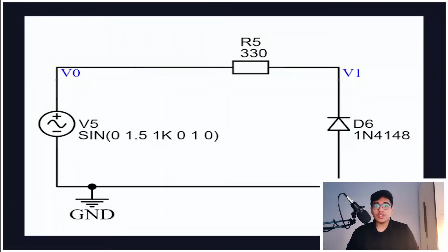I think the working theory is pretty obvious if you paid attention so far. Since a diode only allows current through if it's in forward bias, in the first half cycle, the current is passing through, whilst in the next half cycle, it is not. This is why there is no voltage below 0 volts, as in the second half cycle, current is not passed through to the load. The case is reversed for the negative half-wave rectification. Usually, this circuit is used to change AC sources into DC sources.